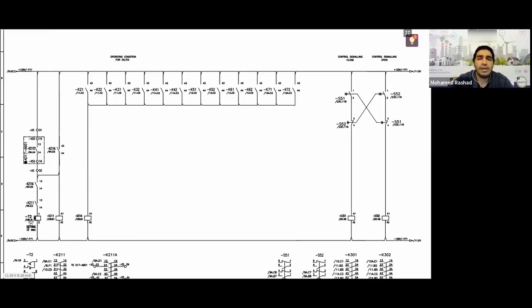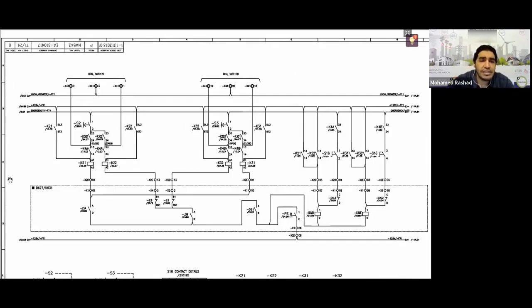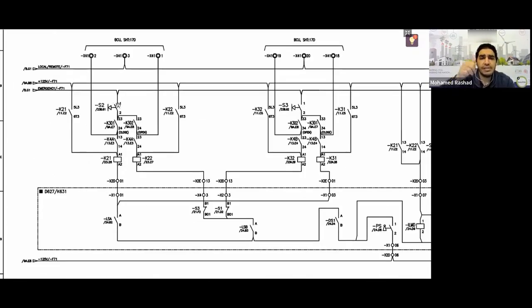That's number one. Number two, if you disconnected the direct DC, when you gave the select close here and activated K21, didn't K21 latch onto itself? Right, why? Because as soon as you remove your hand from the command, whether from emergency, local, or remote, it only sends a pulse from the PCU. In the end, K21 will be reset, which is why it latches onto itself until the switch reaches the end of its journey.